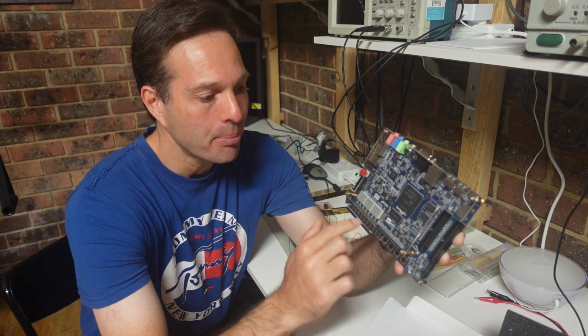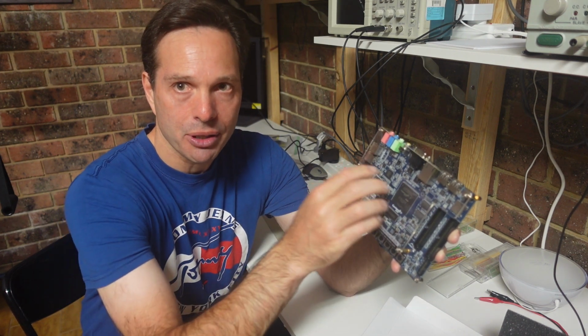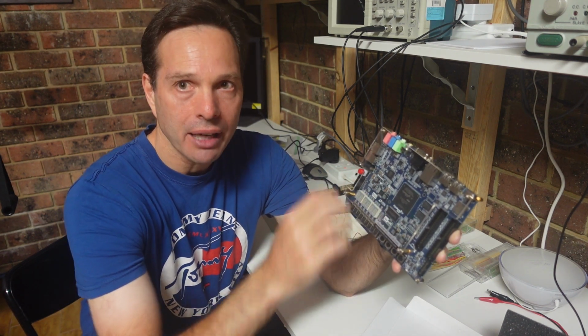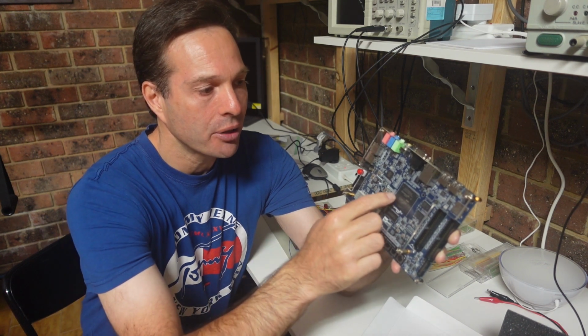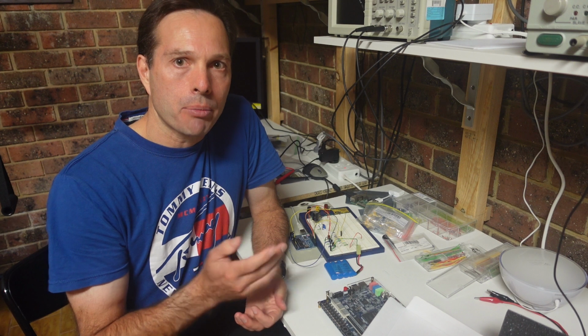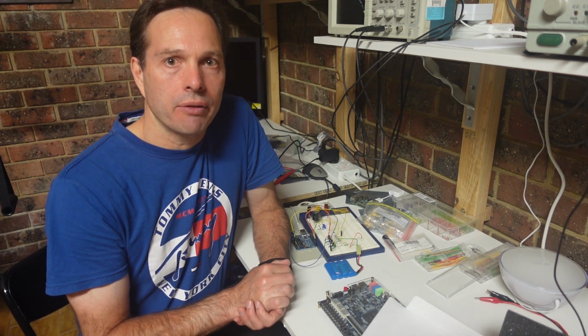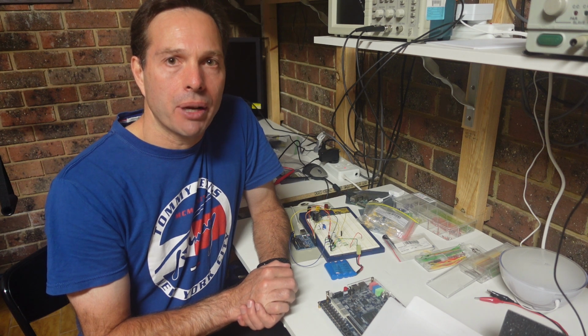The wiring up is done separately from Verilog. Verilog describes the circuit. Another part of the Quartus software is where you do the pin assignments, because they're different things. Going back briefly to the design of digital circuits, when we do it using Verilog, we have an important benefit.